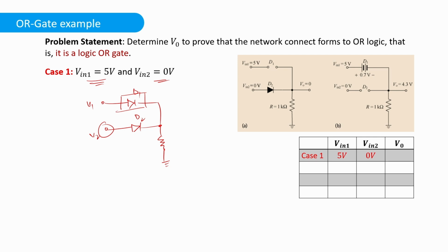But it's obvious to us from this figure that the diode is in forward bias condition if the battery source is connected in a way that we have positive terminal connected with the positive terminal. If in case we have a negative terminal connected with the positive terminal, we will have this situation. We will have a circuit over here like this, right? Negative terminal, positive terminal, and here we have this diode, right? So we can see here that the negative terminal is connected with the positive terminal of the diode, so there will be no flow of current.